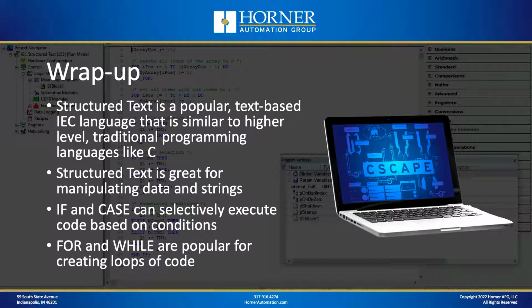All right, time for our wrap-up. So the important points we covered today are the fact that structured text is a popular text-based IEC language similar to higher level traditional programming languages like C. It's great for manipulating data and strings, and there are several useful instructions and statements such as if, case, for, and while, which we demonstrated for you.